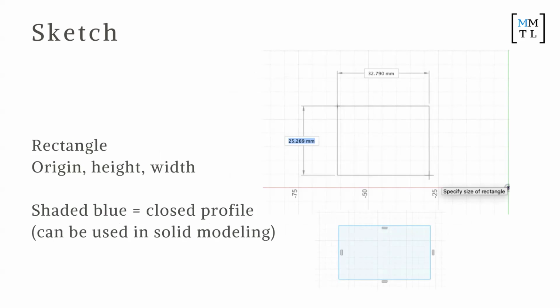Sometimes you're gonna run into the problem where you've accidentally moved your viewpoint and it's no longer in an orthographic view where it's flat. So what you're gonna want to do is click on the view cube, move it around, and go back to the surface where you're drawing the sketch. That way you know you're sketching on the plane that you've clicked and it's accurate 2 dimensions.